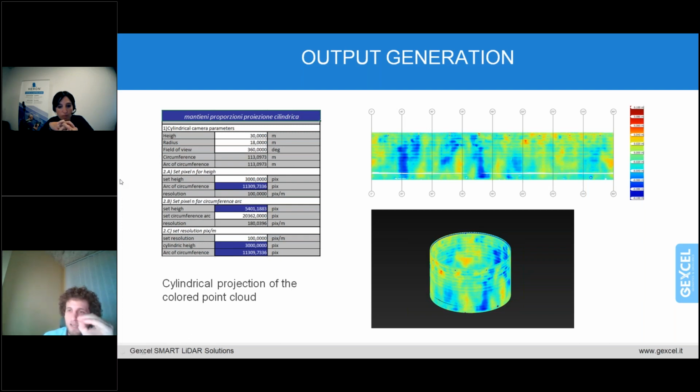Each point can be calculated according to its distance from the as-planned state, or if you choose otherwise, because it has some tweaks and twitches within, it can calculate distances along axes, x, y, or z, or it can be absolute values, signed values, so you get quite a flexibility, let's say. And when you have it, it looks like this color map on the top, or first phase, it's going to be getting a point cloud, but with the deviation color.